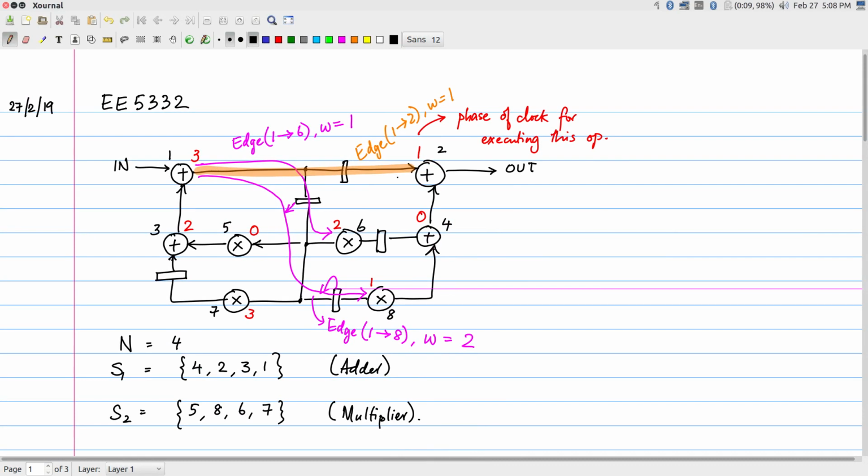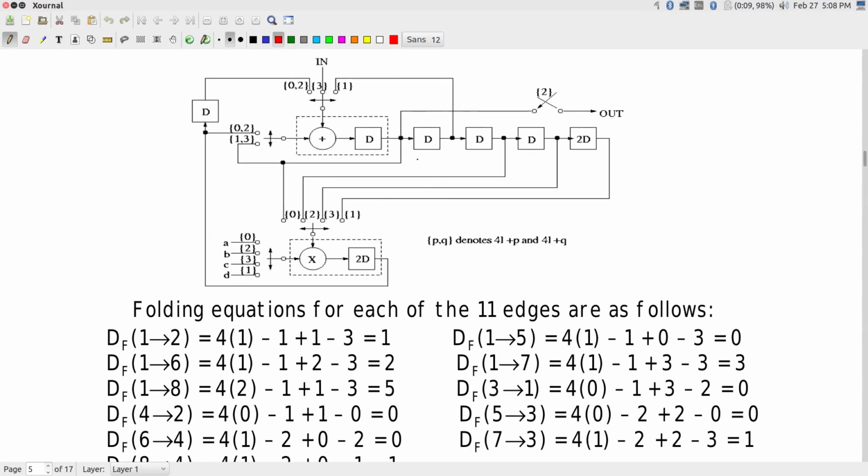So operation number 2 is an addition, right? It occurs at time 1, phase 1 of the clock. So that means that I should basically be interested in what are the inputs coming to the adder at phase 1. Okay. I can see that this is one of them and this is the other one. Okay, so where are they coming from? This one is basically coming from the adder output over here, and this is coming from the adder output over here.